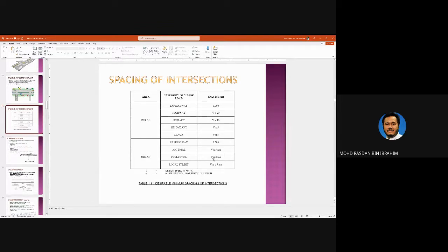So what is the design speed for that road? I'm also lazy to open it. Let's say how much? 60? Let's be conservative, say 80. 80 times 2 is 160 times the number of lanes in one direction. 2 lanes or 3 lanes? 2 lanes, right? 160 times 2 is 320. So what we have now is 568. So meaning that it is adequate.